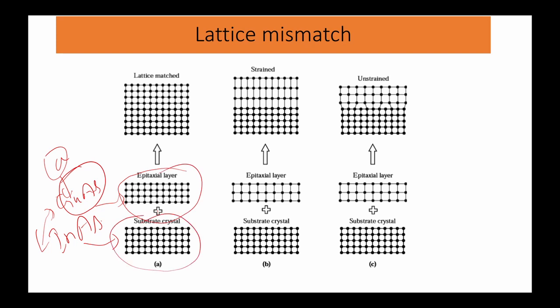In reality, the lattice parameters are different, because of the size of the elements. If the lattice parameters are the same, then there won't be any strain between the substrate and the growing first layer. If there is stress or strain, we will see that in this one. If the lattice parameter A of the material that we want to grow is higher than that of the substrate,